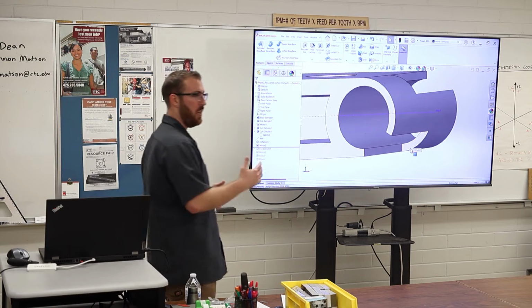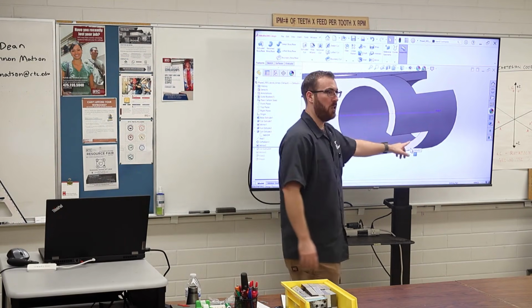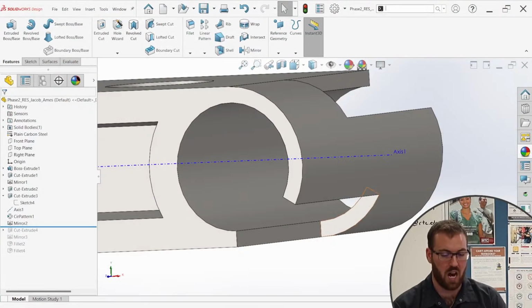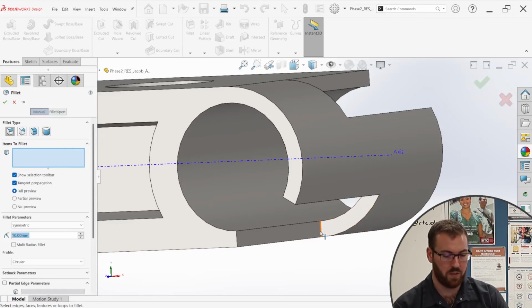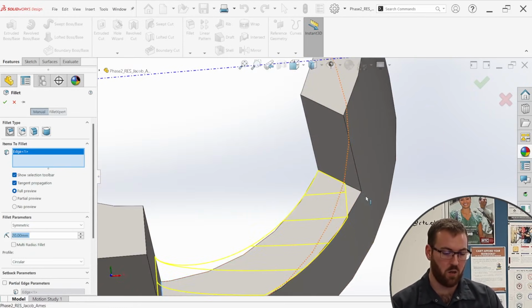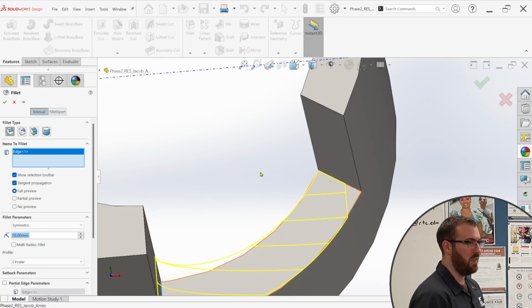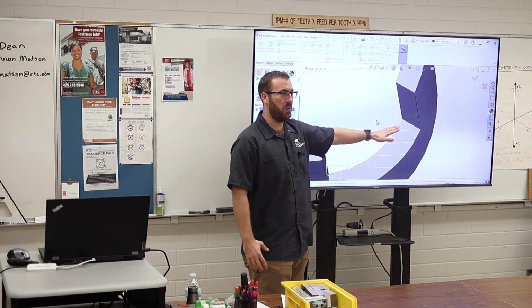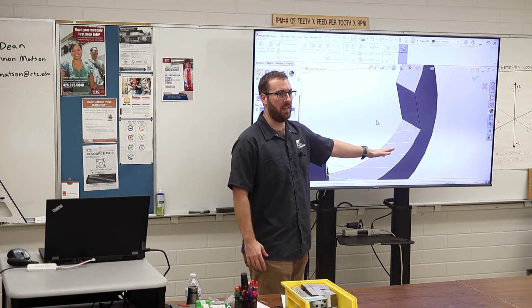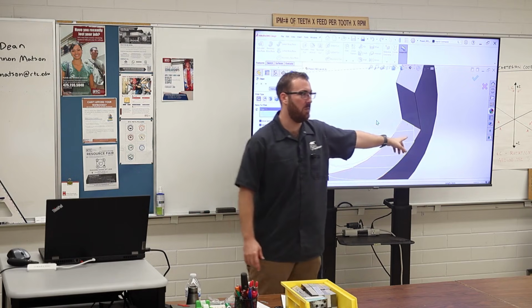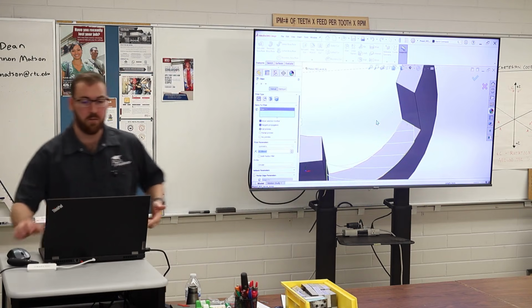Because if you do make the connection that we do need to create a fillet feature here, that's great, but if you try to do it now, it's just a little bit off, but it's enough to mess you up. So if I create a 20 millimeter fillet here, which is the radial dimension specified on the drawing, we actually get early termination because of the existing face. If you see stuff like this where you're creating a feature and it stops sooner than it should, this is probably always a bad thing. Maybe I'm speaking too generally there, but when I look at this, I think that's not supposed to be like that. So we have to pay attention to feature order.